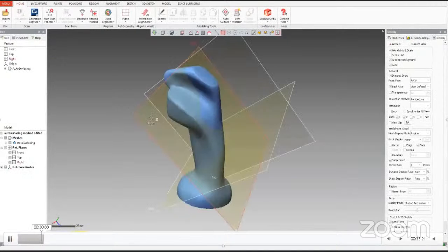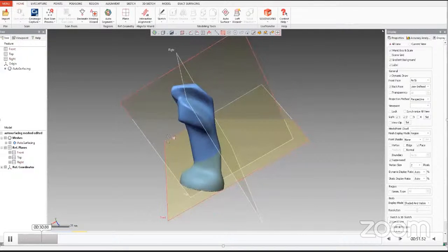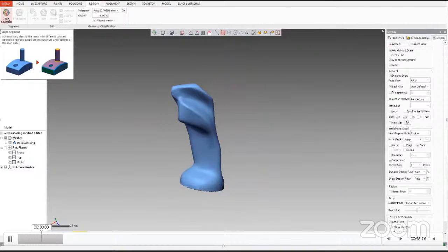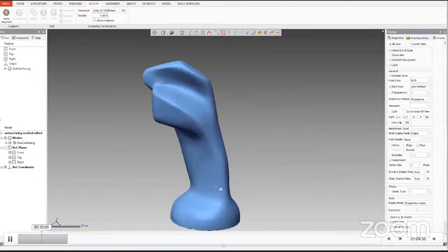In this step, we want to align the reference planes. The reference planes are very important for CAD modeling because they show which is the top view, which is the right view, and which one is the left view. Based on this reference plane alignment, we are able to generate the 2D drawings. And once we have completed the 3D CAD modeling without alignment, we cannot realign the CAD data. It's very difficult for the software to realign the CAD data's reference points.